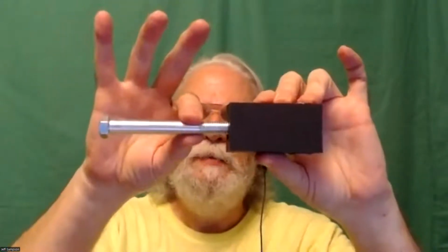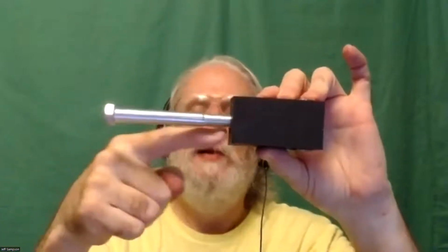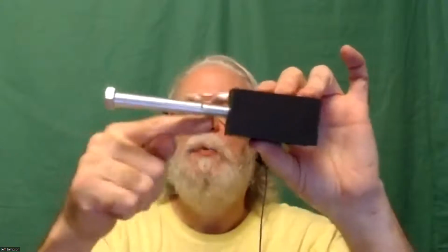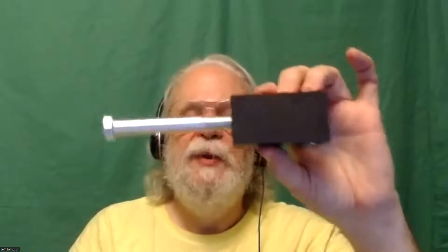The other thing is, if you do this, I've got that bolt screwed in there and then the wheel is on there, it's going to tend to try to unscrew as it drives around. So I might have to put Loctite on the threads or put some super glue on the threads, run it almost all the way in, put some super glue on and crank it down. And then the other thing was, let's see, super glue.